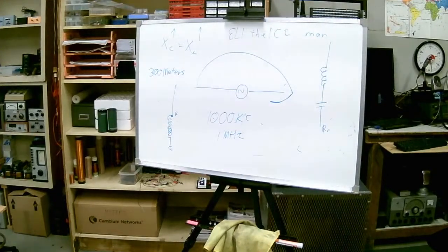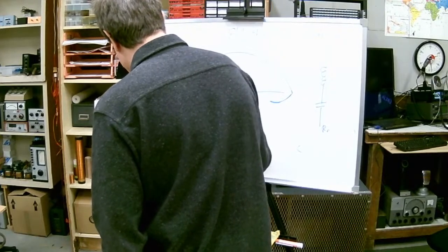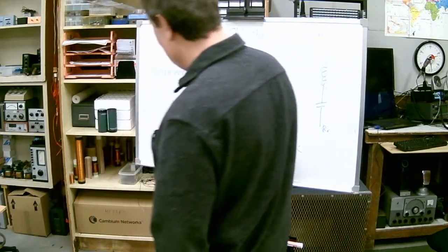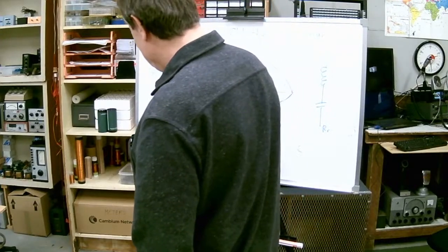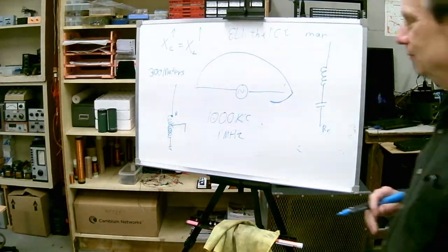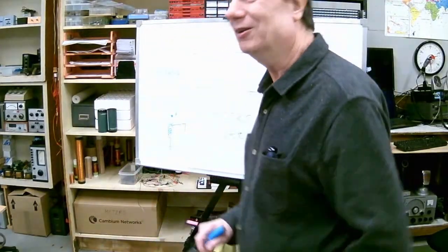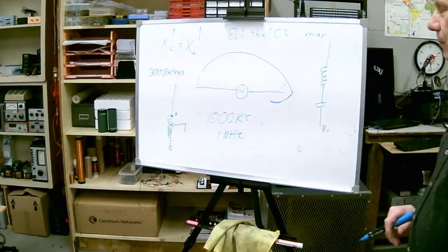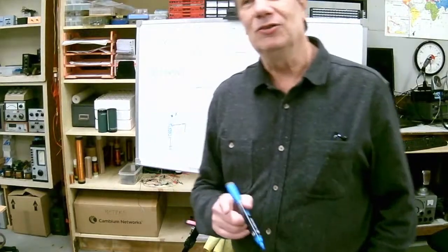What you actually do is you put a tap on this inductor here. You're feeding it right here, because at this point it's extremely high impedance. Down at the bottom is 0, okay? So we pick a tap point somewhere on there where the impedance is usable, what we would normally want to have in a receiver. In factory adjustment they move it, so it's a tapped inductor, like the one you showed us.